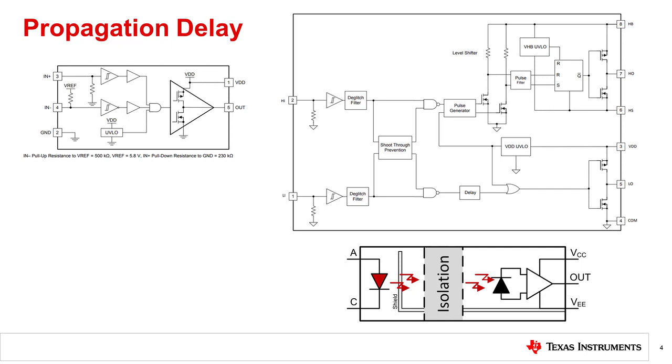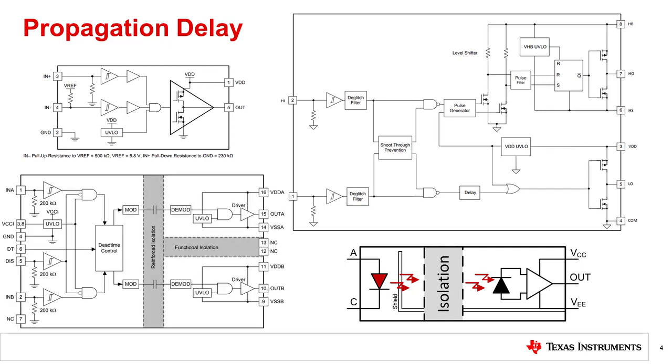More commonly, these design values are relaxed to allow acceptable propagation delay in the low hundreds of nanoseconds at a more competitive price. Capacitive and transformer isolators encode their binary output states on a high-frequency carrier, which can have a period of a few nanoseconds or less. Carrier demodulation may likewise take only a few nanoseconds, though in most cases the overall delay is longer because of internal logic delays and deglitching filters. Not all manufacturers implement their isolation modem the same way, even if they use similar technology. In other words, propagation delay is not set by an isolation medium, but by a technology using that medium with specific constraints.